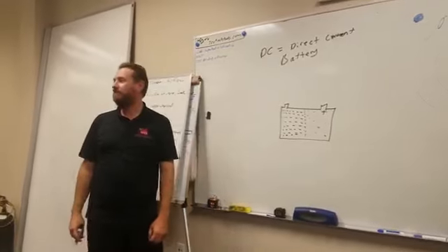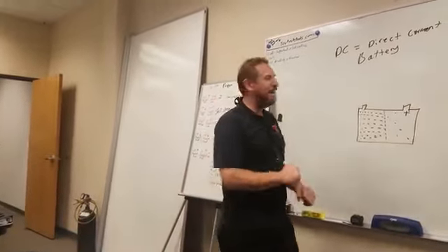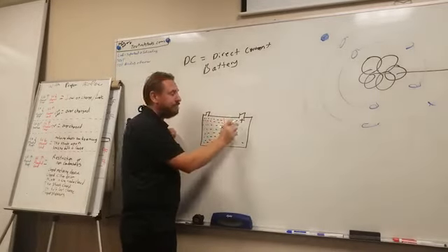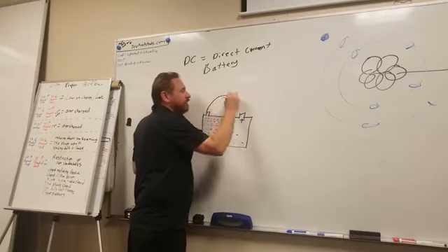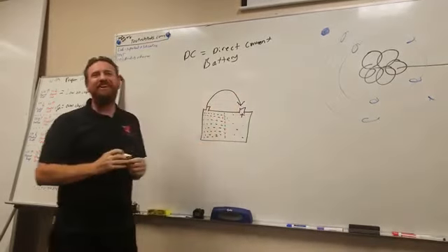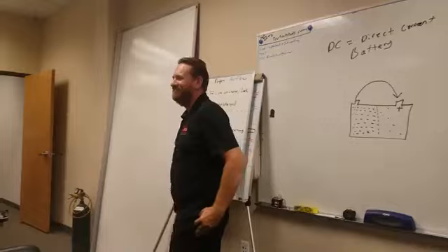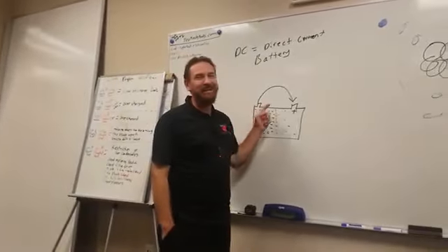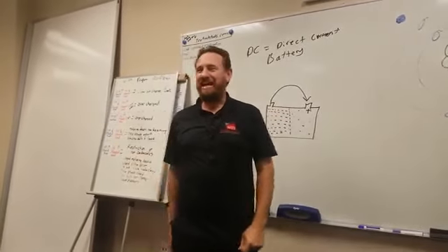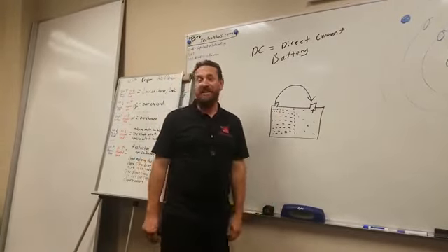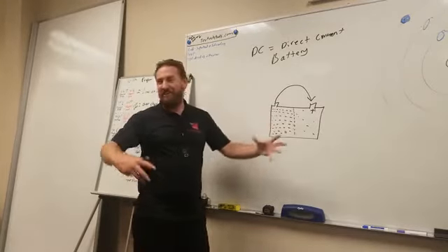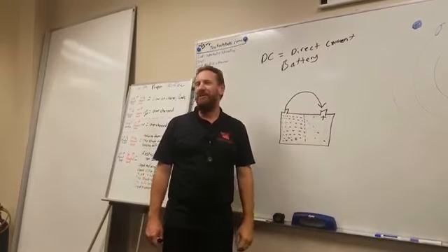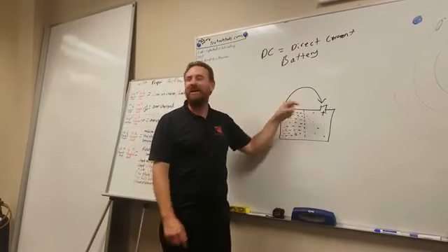There's not enough electrons. So, in Earth, it wants a balance. So, these negative electrons are going to want to flow over here to the positive side. So, with electricity, all DC, your car batteries, and everything else, the electrons are actually flowing from negative to positive. The chassis ground that we all think of as ground is not really ground, it's chassis, right? You're energizing your whole entire car, and those electrons are wanting to flow to the positive side. What we call the red wire, the positive side, is really where they're trying to get back home to.